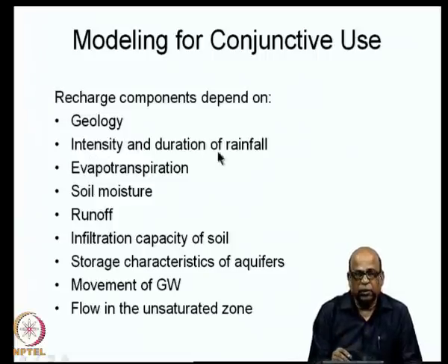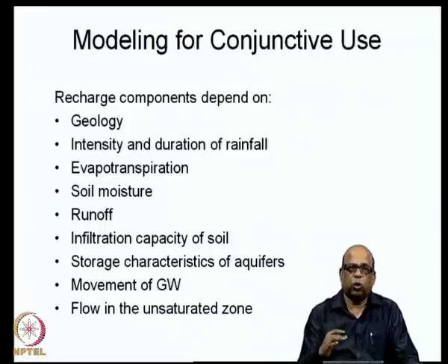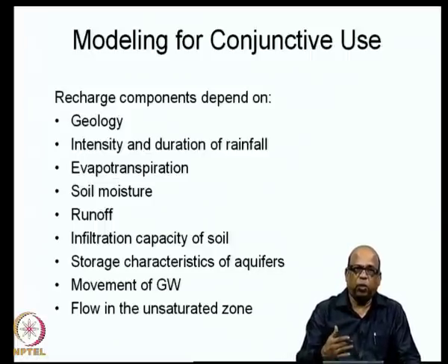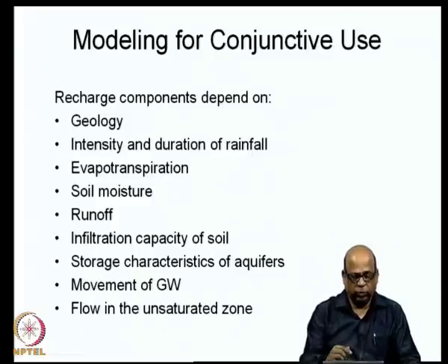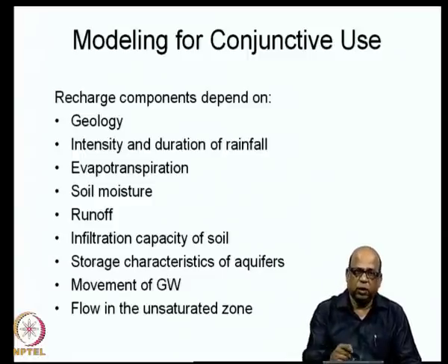Then the intensity and duration of rainfall, evapotranspiration, soil moisture, runoff, infiltration capacity, storage characteristics, movement of groundwater in the aquifer, and then the flow in the unsaturated zone, that is the vadose zone that I just talked about, and so on. So, there are ways of computing the recharge, which generally is based on all of these factors. We will not go into those details, we will simply assume that we know how to compute the recharge for a given data which pertains to all of these amounts.